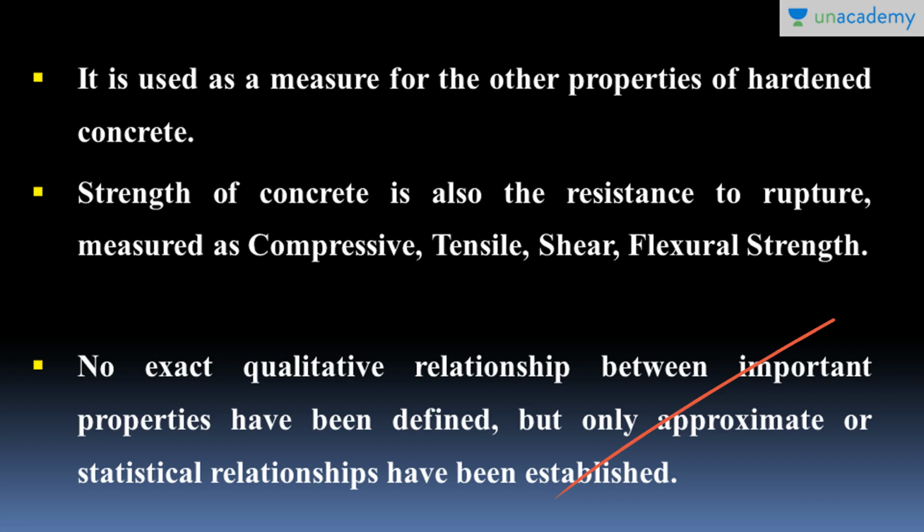The compressive strength increases when the size of the specimen increases, but the modulus of elasticity decreases. So it's like an inverse proportion. In some other cases, compressive strength doesn't provide a clear result in the case of freezing and thawing. Also, concrete containing about 6% entrained air, though relatively weaker in strength, is found to be more durable and denser than the stronger concrete, but it doesn't have much strength.